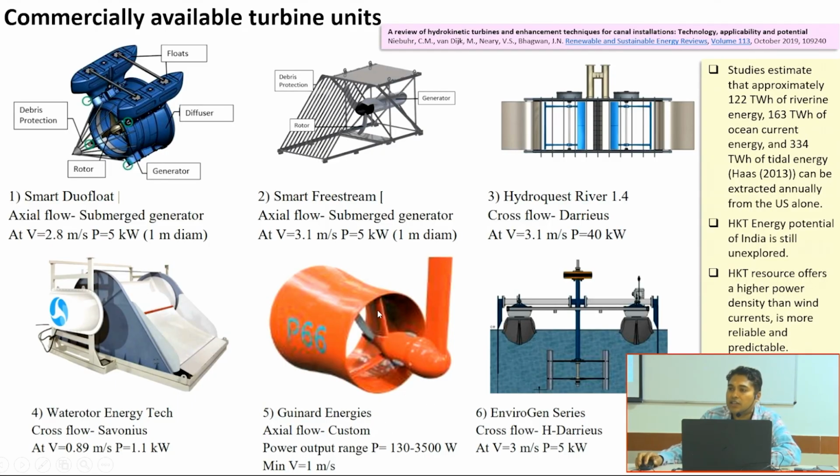This is again another axial flow turbine. Now if you see this structure, there is a capsule sort of part. Maybe there is a bevel gear arrangement inside it, so that the rotation of the shaft can be transferred like this. We have discussed in the last class that the whole system will be immersed into the water. Here also the whole system, up to this part, will be immersed into the water. This is the only floating device. So the structure indicates that this will be installed inside the water, but with its self weight it will somehow be stuck in the river bed. So there is no floating part available here.